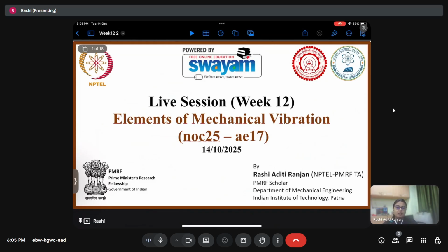So today's live session is about what has been covered in this week's lecture, which is about continuous system. Up till now, how we started the course was we first worked upon modeling of a continuous system as a single degree of freedom system. Then we talked about how to deal with that kind of a system, how to find out the natural frequencies, and how the system is going to respond upon application of some external force, which can be impact loading, a sinusoidal force, or a continuous or periodic force, everything of that sort.